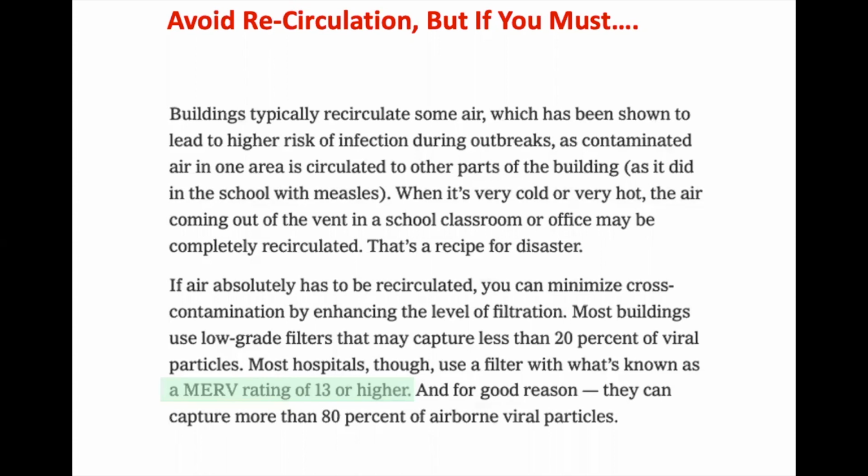Well, that may work when the temperature is right. You can open it up and just call it economizing. But when it gets cold, which is absolutely possible since we'll still be dealing with this in the wintertime next year, and you open that up, you're not going to have enough heat capacity to heat up 100% outside air when it's only designed to do 20% outside air now.